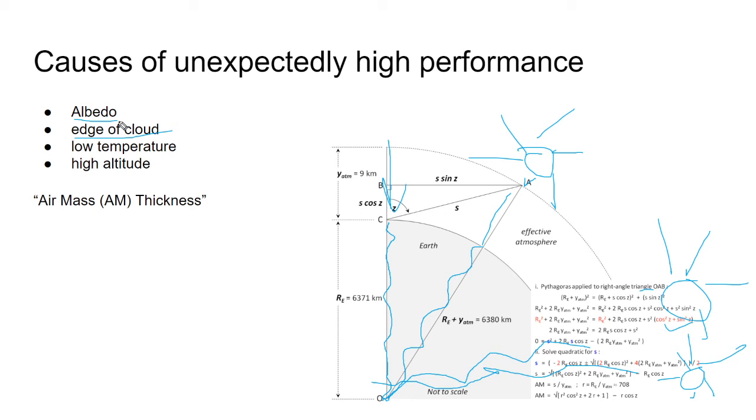To reflect sunlight off the bottom of a white roof back onto the bottom side of a bifacial solar panel, yes, that does increase performance, but we're talking about maybe a 10% increase in performance. Best case scenario, 20%. And I mean, that's for double axis trackers on top of a field of snow.